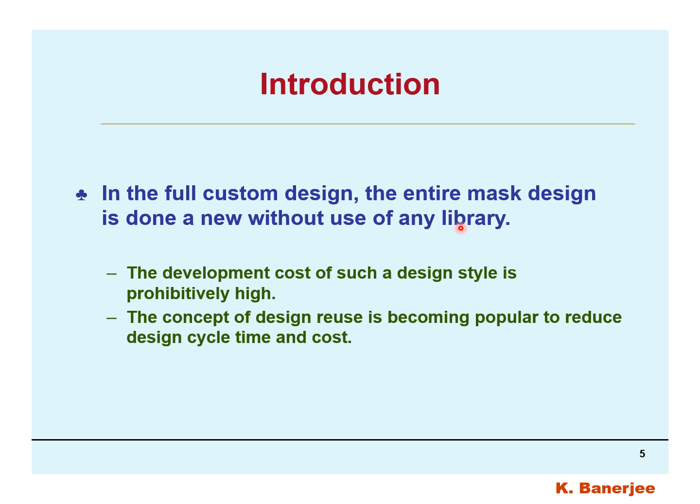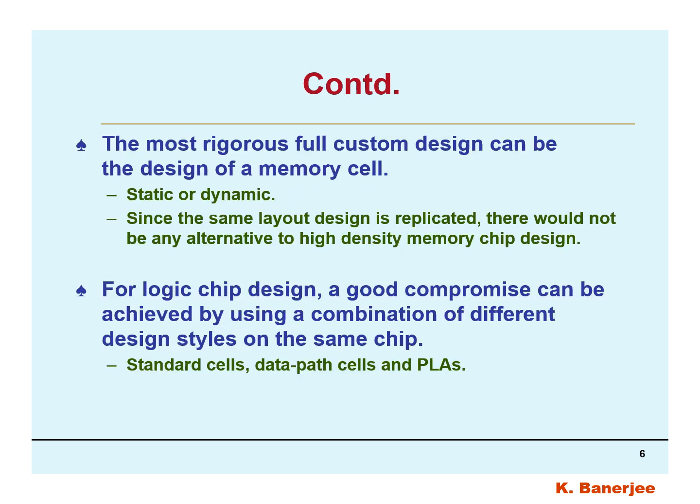This method potentially increases the performance of the chip and minimizes its area, but it is very rigorous to implement. So circuit complexity, designing complexity is very high. The development cost of such a design style is obviously higher. The concept of design reuse is becoming popular to reduce design cycle time and cost. So moving forward, the most rigorous full custom design can be the design of a memory cell. It can be static or dynamic. I'm not reading out all these things. Let me discuss that.